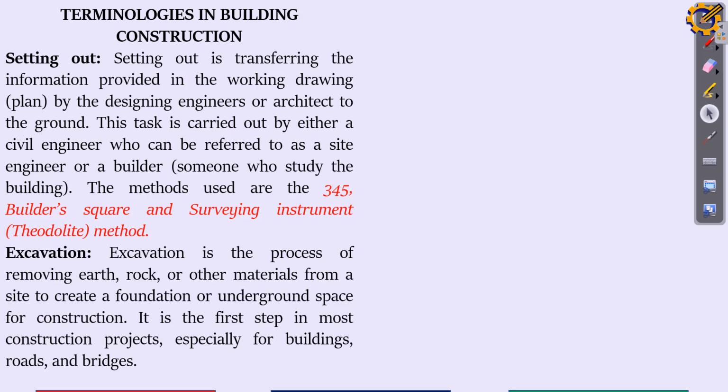Another one is excavation. Now, after marking the length, breadth, the wall position, and the likes, the next thing is you start excavating, that is digging the ground, digging out those shapes which I've actually marked out. And in a setting out scenario, you can start marking with chalk on a construction. They make use of profile board and building line in most cases alongside the pegs. That's when you see them carrying all this wood that has a pointed mark.